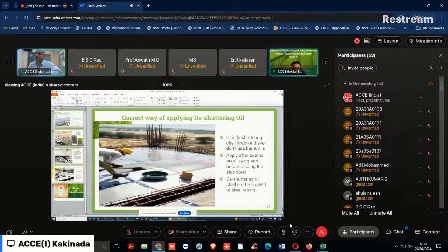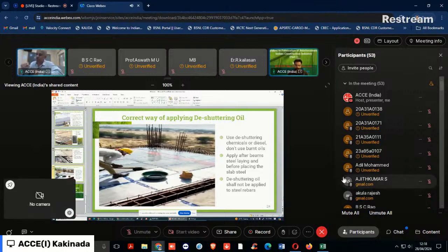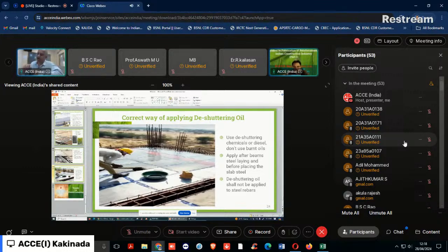And also this is a minute thing, but a very important thing. Why? Because in the case of concrete, the compatibility of the strains is important. That is, the tensile strain in the concrete should be equal to the strain in the steel. That is a basic composite material requirement, not only for RCC. Any composite you take, FRP or any other, strain compatibility is important. Once you lose that strain compatibility equation, that is the slip condition, the function of the reinforcement is lost. That is, the two materials will behave as two distinct materials. Therefore, strain compatibility in terms of the no slip condition should exist.